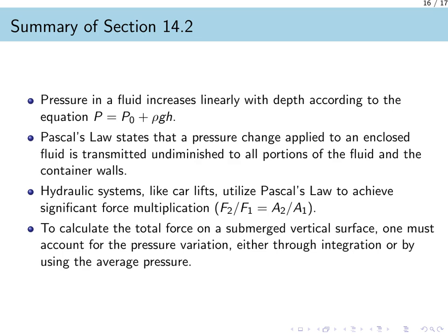Let us now summarize the key principles governing pressure in a static fluid. First, we established that pressure increases linearly with depth. This is captured by the equation P equals P naught plus rho gh, where P naught is the pressure at the surface and h is the depth below it.